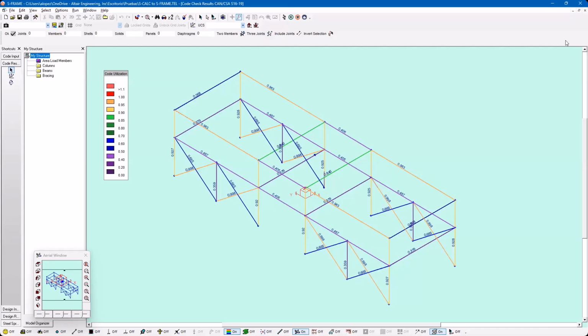It's important to mention something here: S-CALC doesn't directly perform the design checks, although it is possible to write your own custom Python scripts to read in the section data and perform custom design calculations on those automatically. We actually ship this software with an example of this.